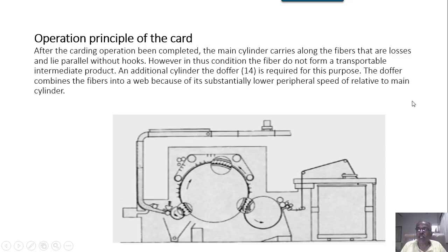In other words, whatever material is carded, once we have fed it here, right from here to this particular place, carding will take place in this region. Now here, on the feeding side, this will slightly tear apart the stationary flats, the wire covered flats.